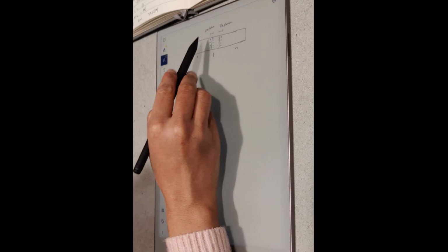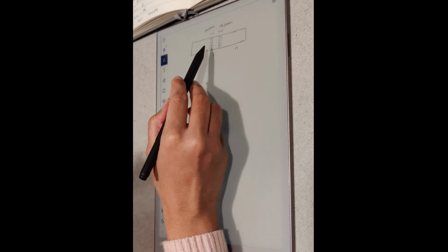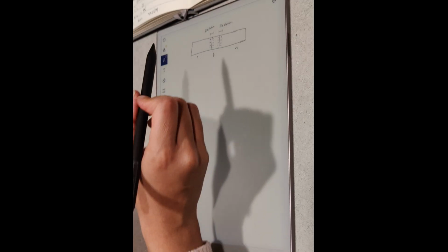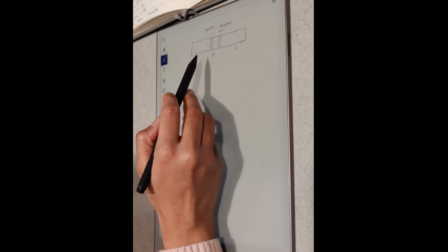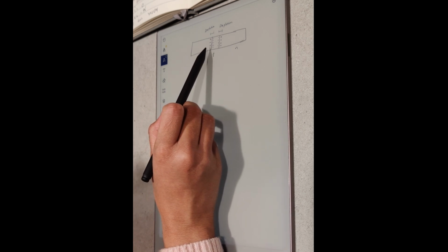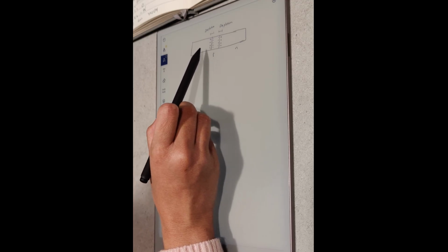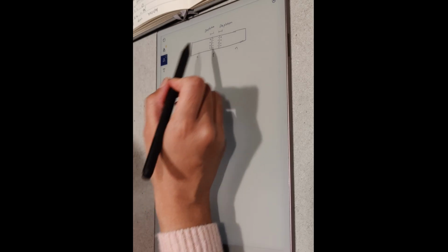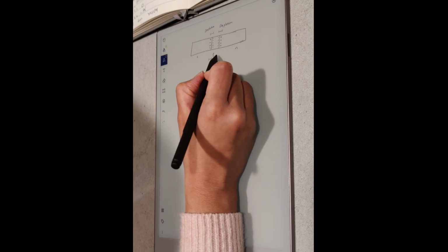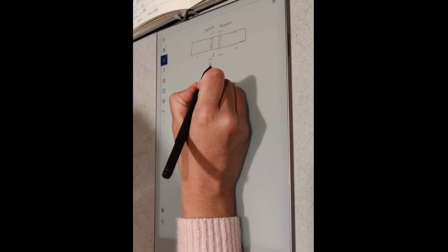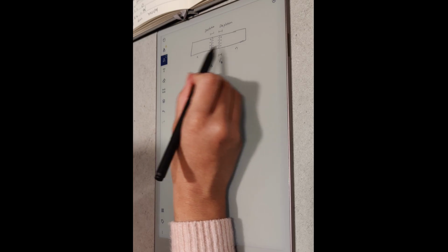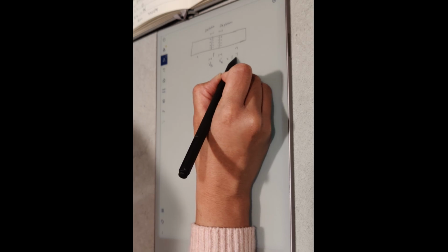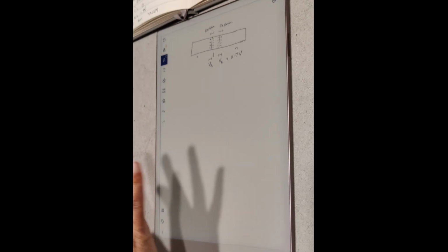Now, in this region, we will have a potential barrier because we have created this electric field due to the charge. So therefore, once enough electrons and holes have combined, no more electrons or holes can move or cross this junction. So we will have a potential barrier created here, and let's just say potential barrier is VB, and if it is silicon semiconductor, then the value of this potential barrier is approximately 0.7 volts. All right, so far so good.